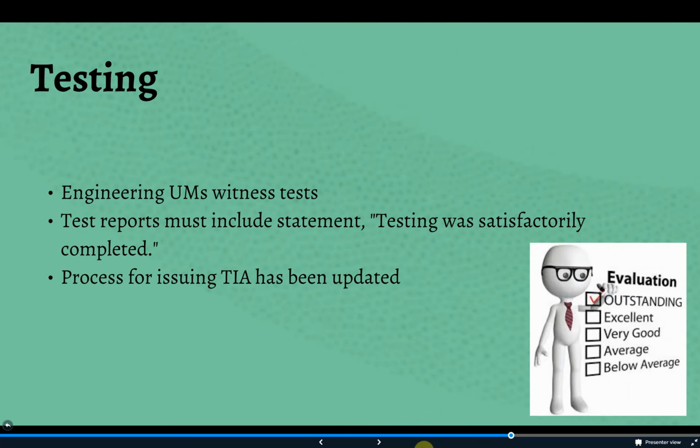change, providing a new 8130-9. Once an article or installation has been conformed, the ODA can move forward with any testing that may have been identified. A clarification in the manual made in Revision C is that test witnesses are engineering unit members, not anyone else. Westar uses the normal approach to building up confidence through the test program, meaning bench testing is completed prior to ground testing, which is done before flight testing.